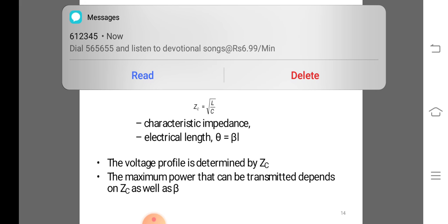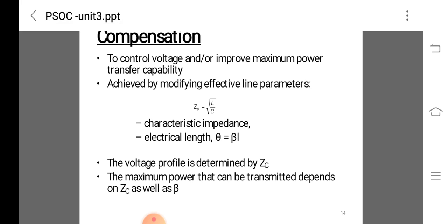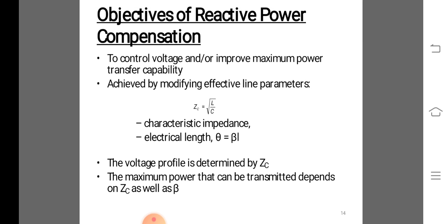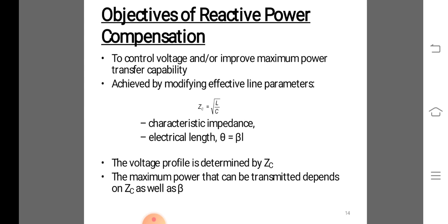The regulator generates firing pulses for the thyristor network in such a way that the reactive power required to meet the control objective at the primary side of the compensator is obtained. The reactor transformer has practically linear characteristics from no load to full load condition, thus even under overvoltages, hardly any harmonic content is generated due to saturation.